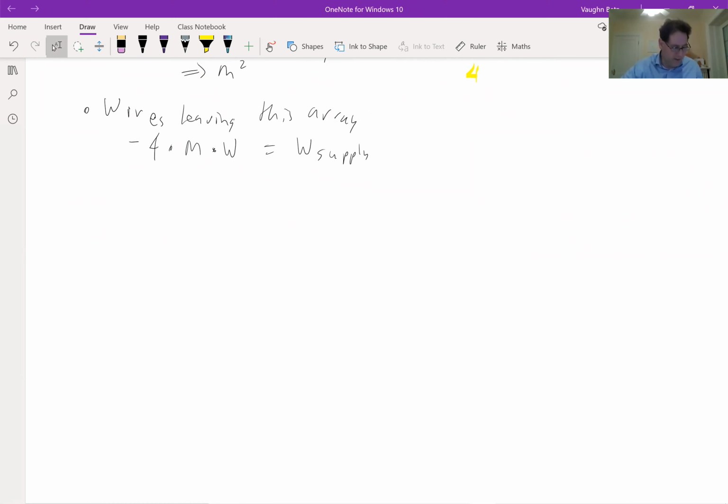All right, so we now need to compare that to what Rent's rule says we're going to need. Rent's rule, remember, says the number of terminals going into some cluster or group of logic is equal to some constant times the amount of logic, which Rent wrote in terms of gates, to the Rent exponent, P. So this exponent is between 0 and 1. If I can just rewrite that, C is an arbitrary constant, so I'm just going to make it a new arbitrary constant, C prime. And that's going to let me change my units of logic from gates to basically logic blocks. The number of logic blocks I have is M squared.